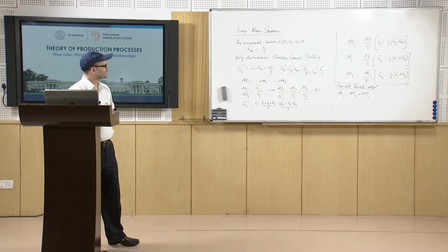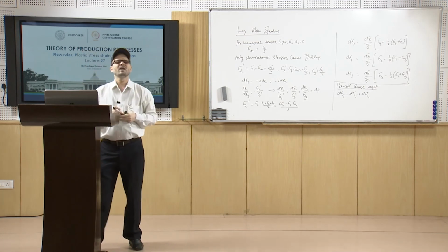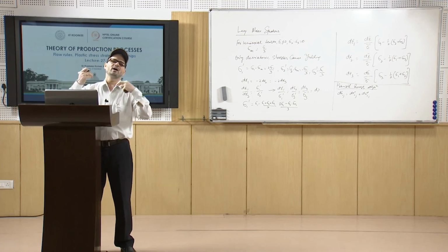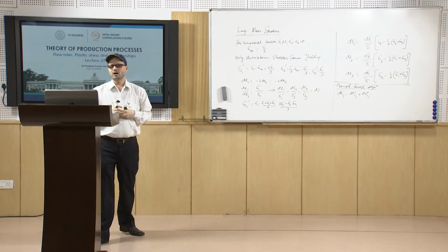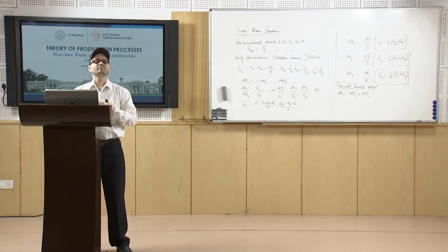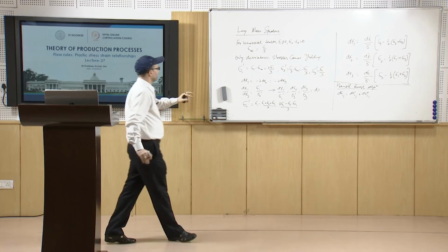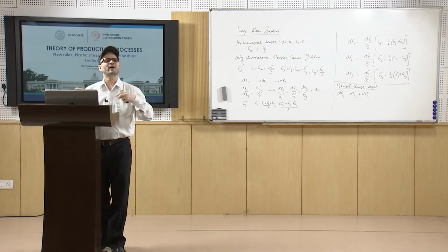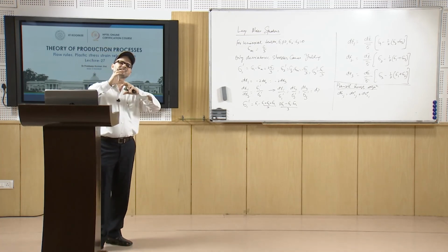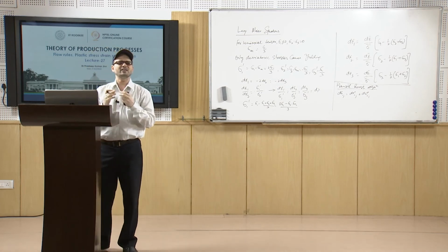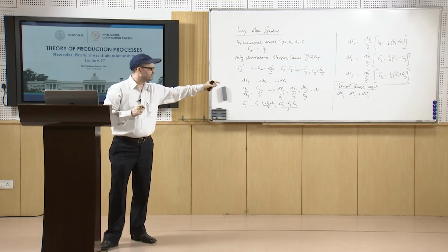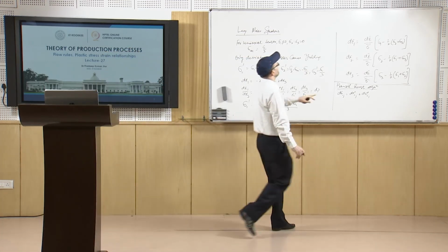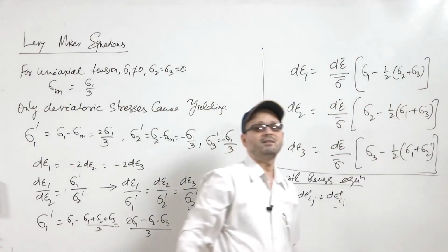Now, for the elastic strain, we have studied the strain tensor, and d epsilon ij elastic can be taken as equal to (1 plus nu) by E times d sigma prime ij, plus (1 minus 2 nu) by E times d sigma kk by 3 times the Kronecker delta ij. Similarly, for the plastic part, we get it from the Levy-Mises equation.